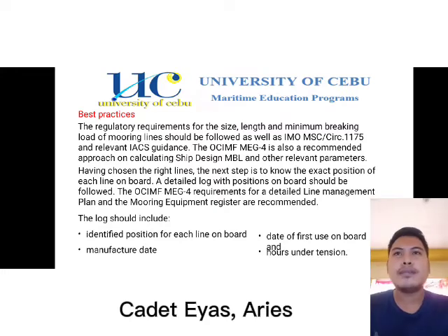The last one is the best practices. The regulatory requirements for size, length, and minimum breaking loads of the mooring line should be followed, as well as IMO MSC.1/Circ.1175 and relevant IACS guidance. The OCIMF MEG 4 is also a recommended approach on calculating ship design MBL and other relevant parameters.